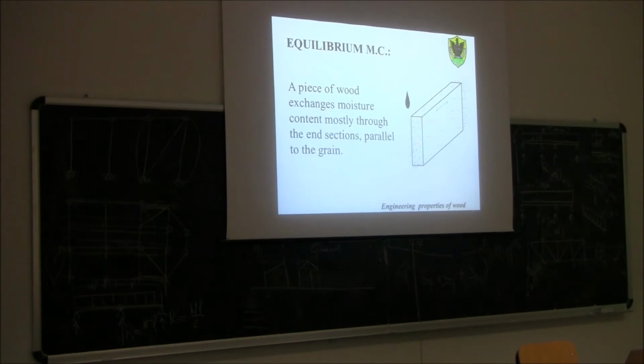Why? Because of course our cell lumens, our fibers, are oriented this way. So it's much easier for the water to go inside the wood in this direction, because it will find directly the straws, the free channels, rather than in this other direction.